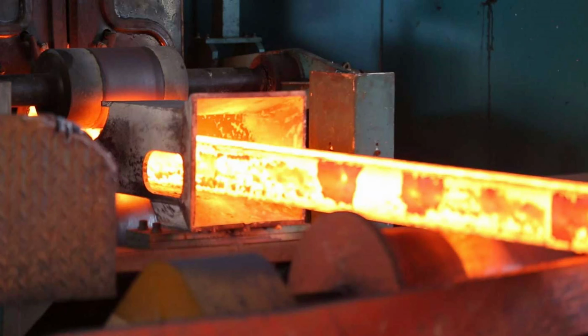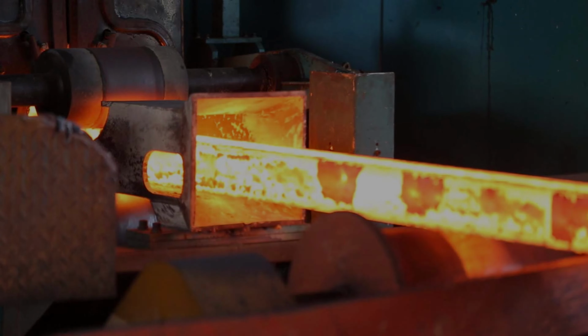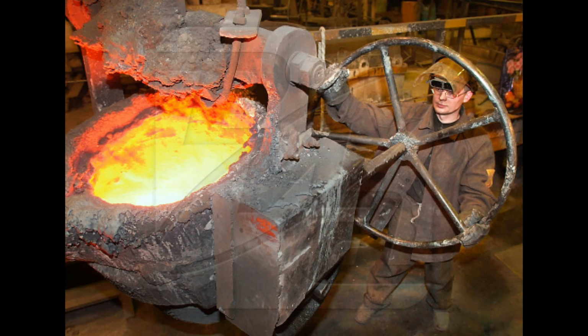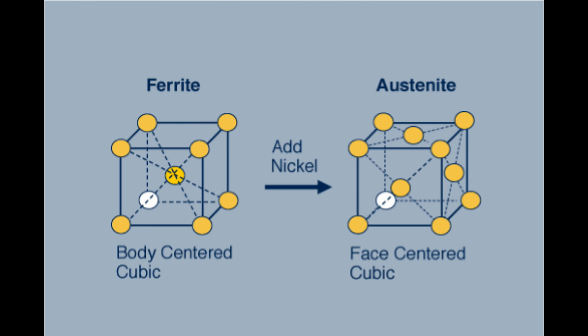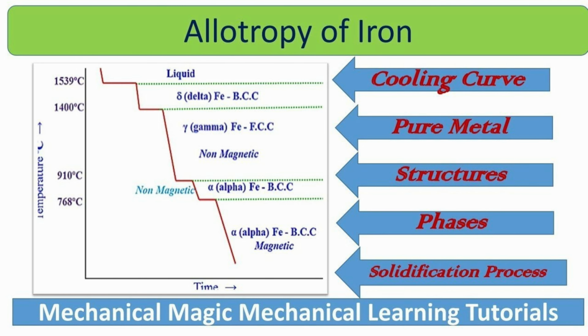So if I heat steel, most carbon steels, for example, if they're heated above 1550 degrees Fahrenheit, they become non-magnetic, first of all, and that iron transitions from body-centered cubic crystalline structure to face-centered cubic. And in the parlance of metallurgy, at that elevated temperature, it's called the gamma phase.